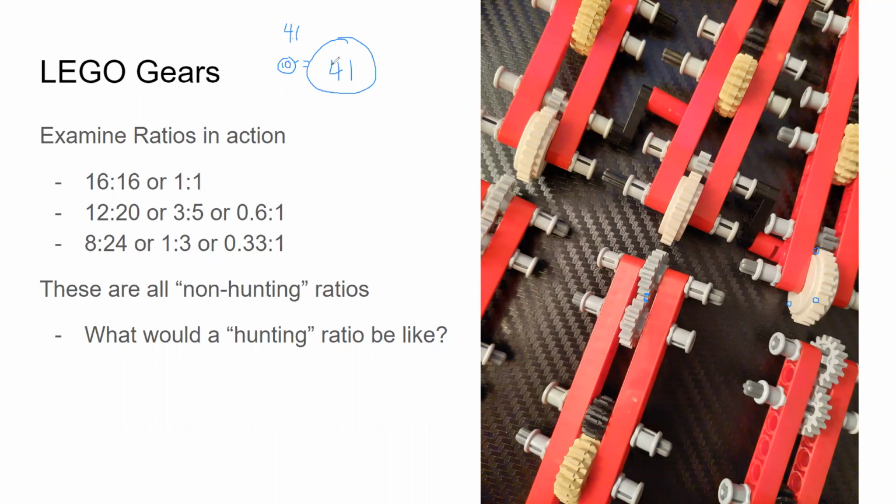So if this tooth right here were bad, it would mesh into these 2 teeth and it could damage those teeth. But it would take 41 rotations of this tooth to mesh up with these 2 teeth again, right there, and cause the wear to affect those two teeth again.